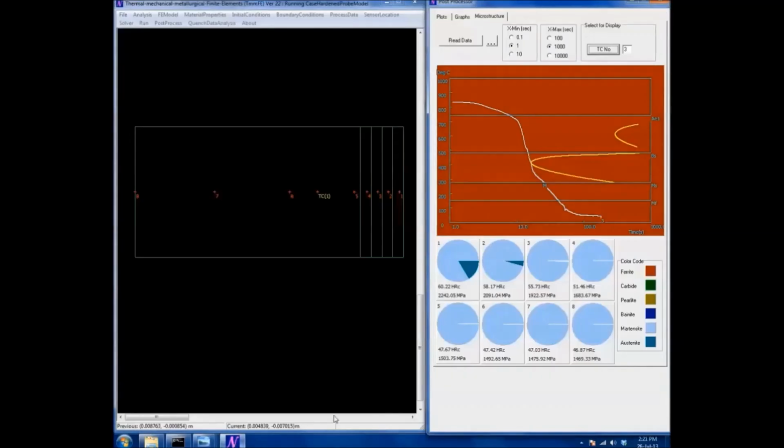The post-processor shows exactly the same trend, with the austenite retained also reduced considerably. The bainite is totally removed from the core because of the higher cooling rates, and both the hardness and the strengths have been improved.